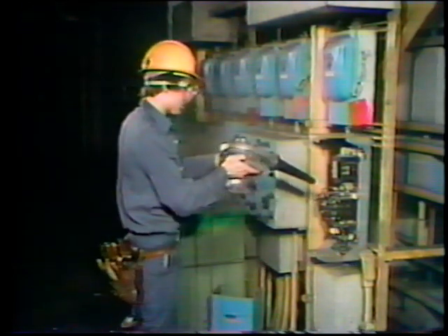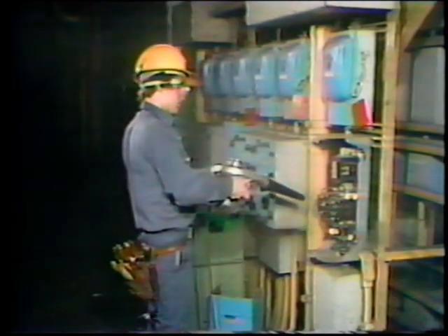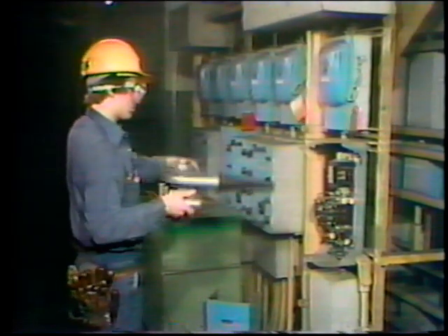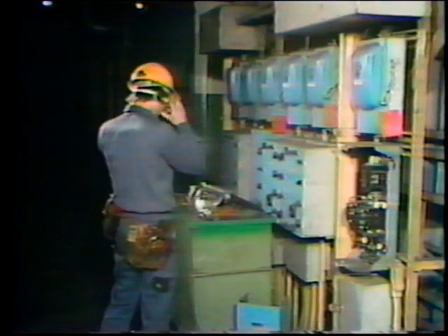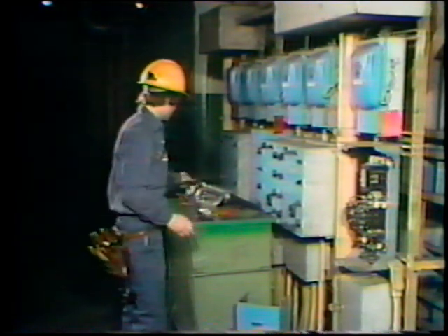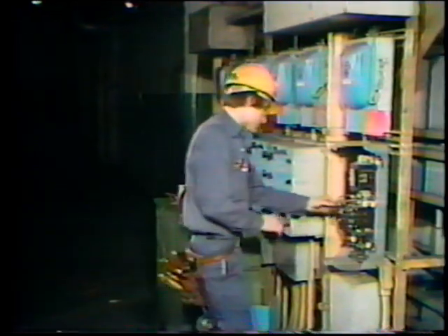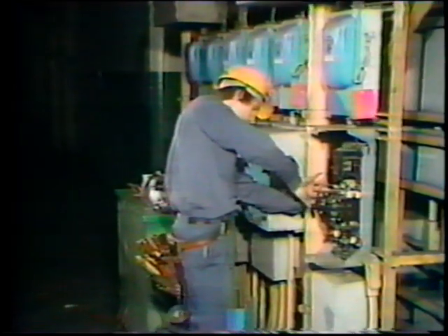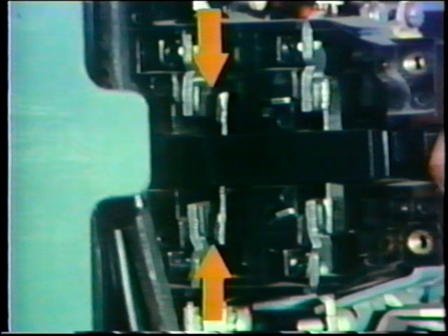It's important to clean the controller thoroughly so that dust and dirt do not hide any part of the controller when you inspect it. Dust and contamination can also contain conducting materials. When these conducting materials get inside of a controller's circuitry, they can cause short circuits or grounds. If dirt settles in between a controller's contacts, it can prevent the contacts from closing.